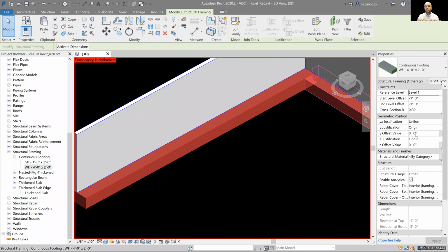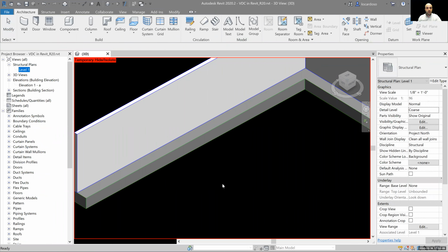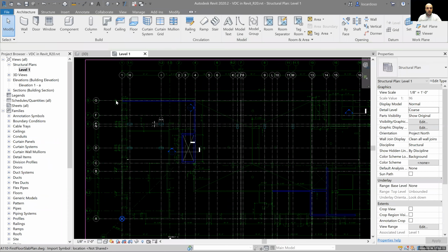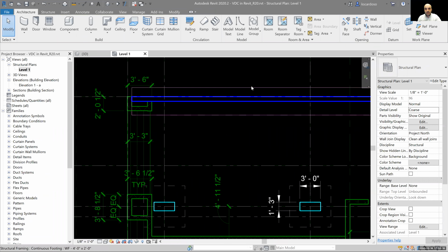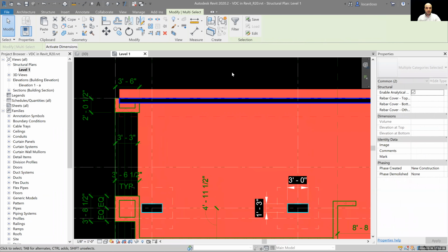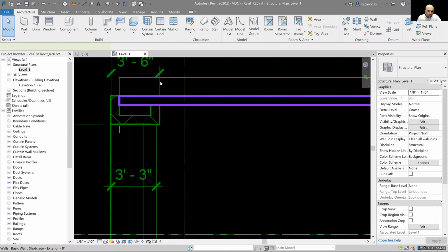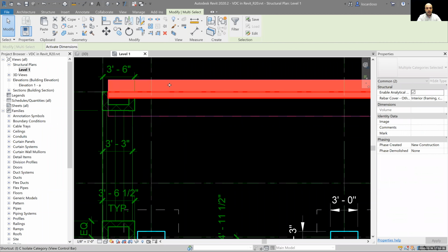I like using what Revit does best, align. So in this case is where I need to go to a level 1 plan view, level 1 plan. And if you want to turn off your CAD background, you can, but I'm going to do the same thing I did in 3D. I'm going to select this beam. I'm saying beam because that's the category, but that foundation element. I'll hover over the wall and I'll hit tab until I can select it. And it looks like that was my floor. So let me get my wall. There we go. And my foundation, and I will isolate element, IE.